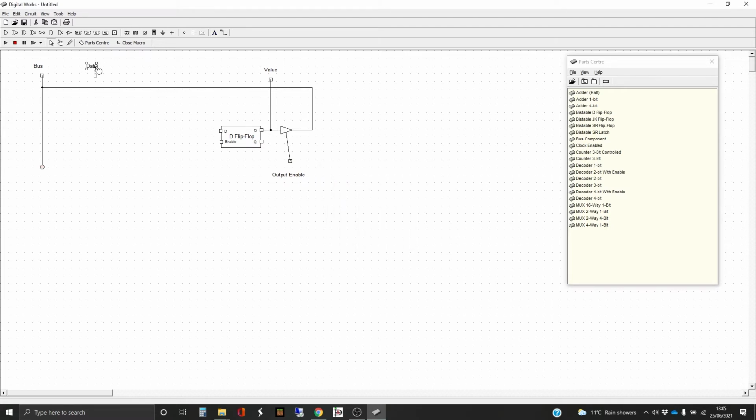And it's going to be fairly straightforward to show which one that we read from. Actually, reading from separate sources is just a matter of enabling one using an AND gate. And in fact, let's stick the AND gates that we're going to need in here. So one's going to be for the bus and one's going to be for the data. I've just put an extra one in by accident.